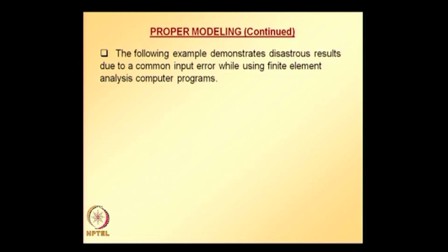The following example demonstrates disastrous results due to a common input error while using finite element analysis computer programs. Sometimes, if we violate the node numbering rule, that for the 2 dimensional case either all the nodes should be numbered in clockwise direction or anti-clockwise direction, some problems with results may arise.